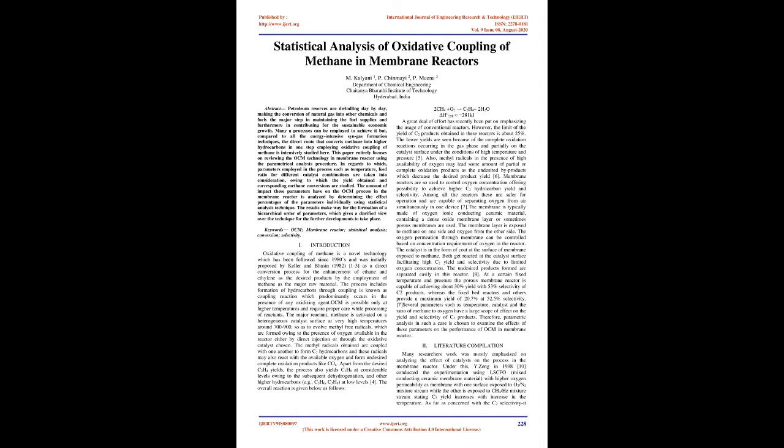so as to evolve methyl free radicals, which are formed owing to the presence of oxygen available in the reactor, either by direct injection or through the oxidative catalyst chosen. The methyl radicals obtained are coupled with one another to form C2 hydrocarbons, and these radicals may also react with the available oxygen and form undesired complete oxidation products like COx.